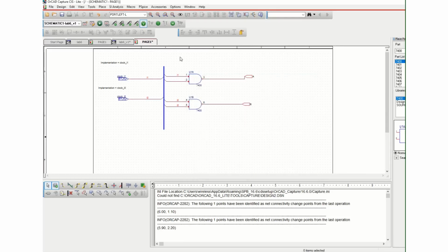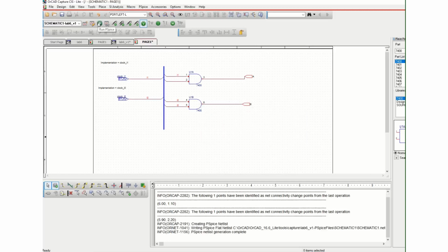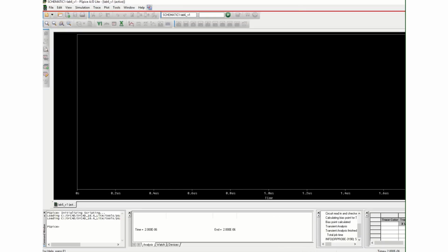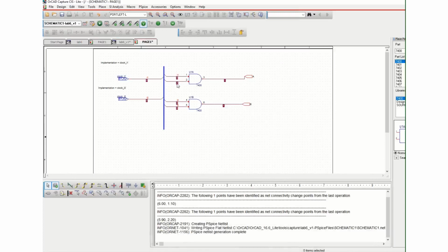Once you run the simulation, you will see almost all the connections have something going on in them except for the one that we did not name. There is a high impedance over there. It shows Z because it is really not connected to anything, because we haven't defined which connection it should be connected to. And that is where we need to name this connection.